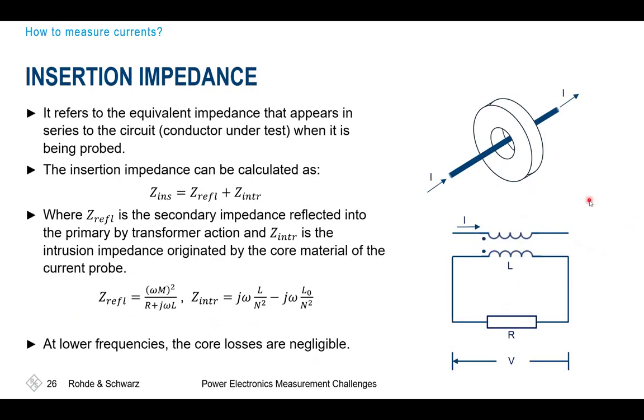Basically, in the easiest case, a current probe is a transformer. As mentioned, we'll have a primary winding and a secondary winding, maybe several secondary windings, around this ferrite core, and then we'll get a resistance that we are inserting into our DUT. If you think about these transformer equations, we'll see that the introduced inductance, or more generically the introduced impedance, to the system is translated with the number of windings in that way. And that's very important to keep in mind.